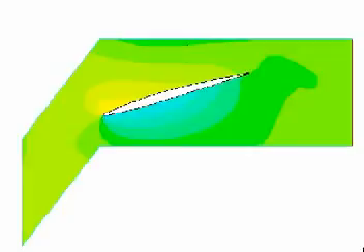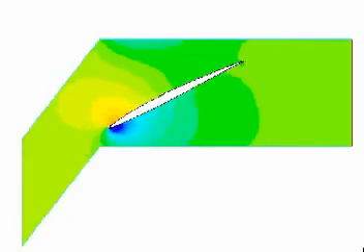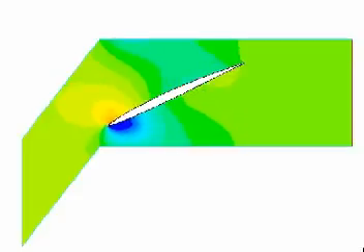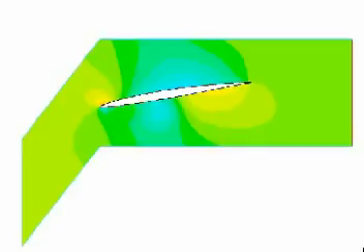In some applications, like this wing undergoing a slow pitching motion, we can approximate the flow as steady at any given instant, even though the flow field is really unsteady in principle. Such a flow is said to be quasi-steady.